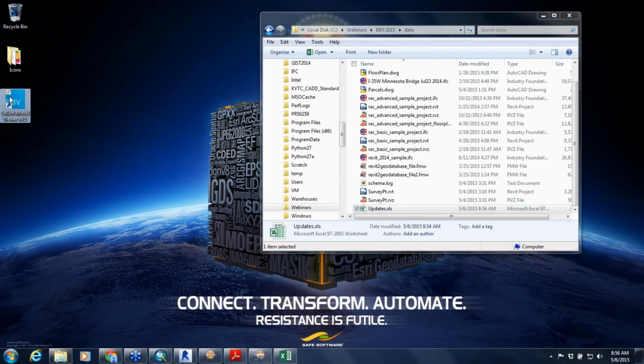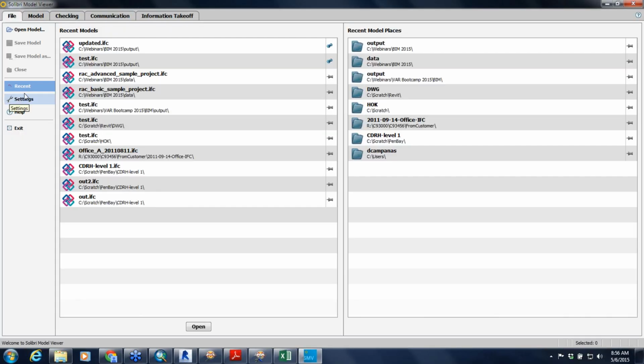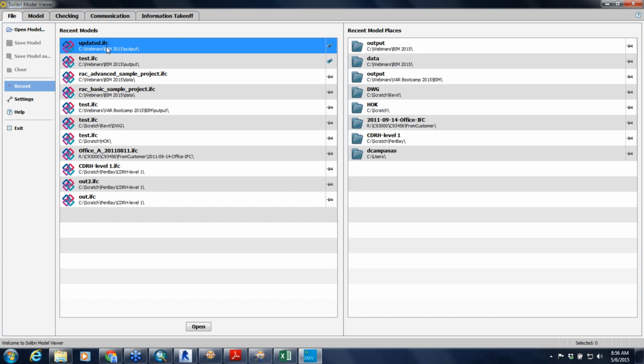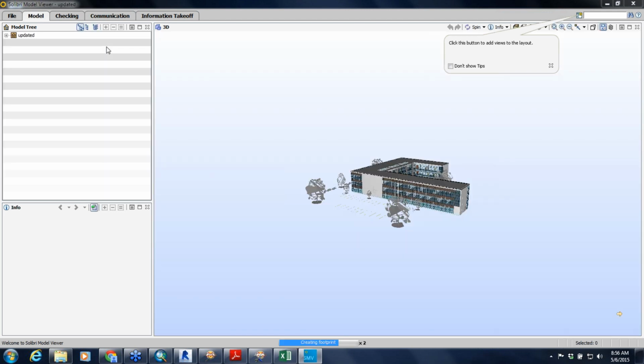Okay, let me just. So, oops. There we go. So we bring up our IFC viewer. Now, I really like to look at the IFC output in a separate reader, just because it lets us sanity test. I mean, we could test with Data Inspector, but if you have to read and write with the same software, too much of our own dog food. Exactly. So it's good to have a separate piece of software. DDS CAD and Solibri are both good ones to use.